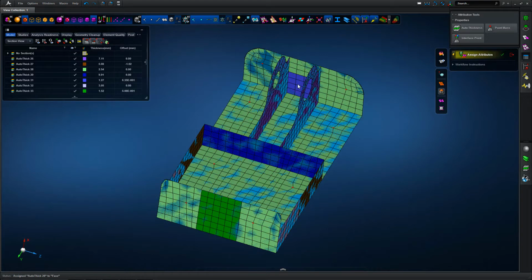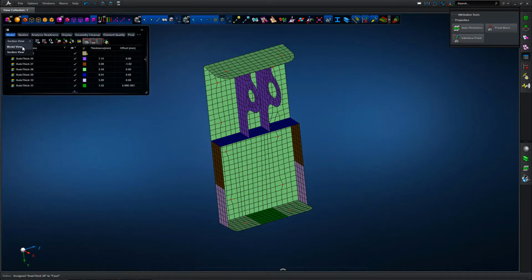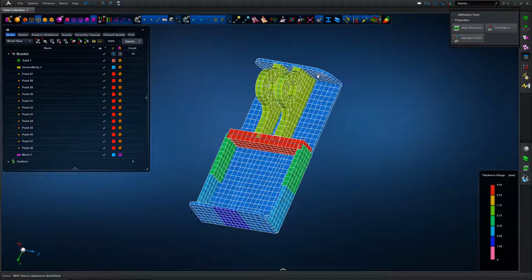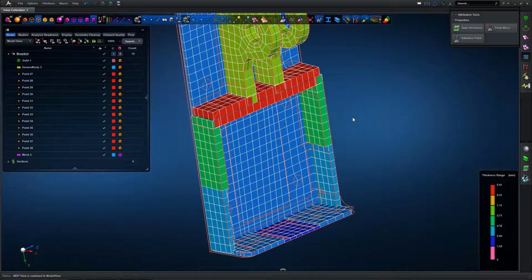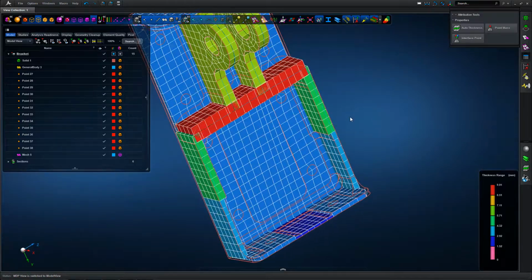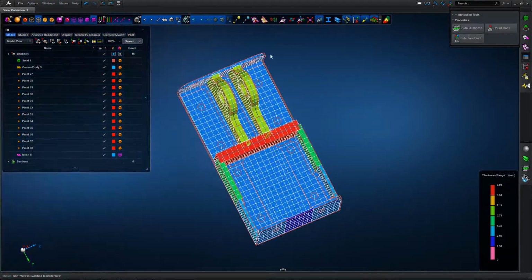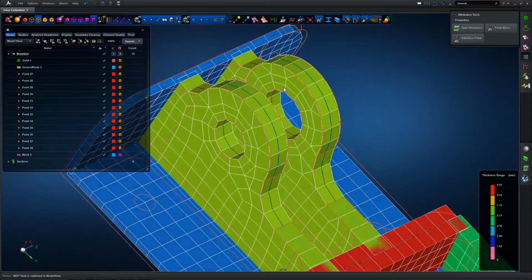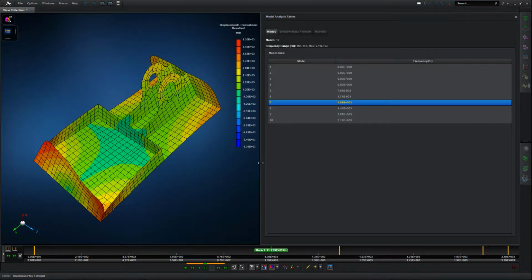what we want, again skewed by some of the fillets in the underlying CAD definition, but we can tidy up the geometry. We're happy with the definition, switch back to model view, and then put the shell thickness on display, and we can see that we've got a much better representation of the shell properties. With the underlying CAD shown, in transparent mode, we can look at the shell thicknesses versus the 3D CAD display. We've got a very good and quick, to this point, definition for controlling those things.